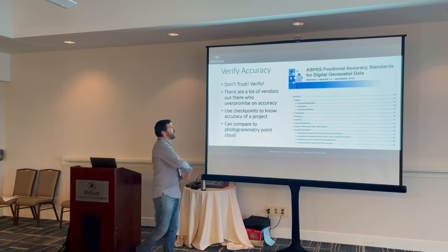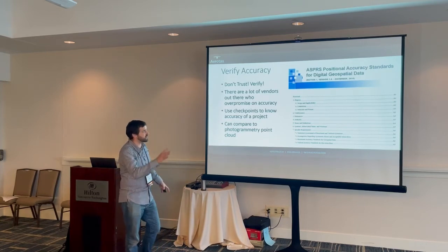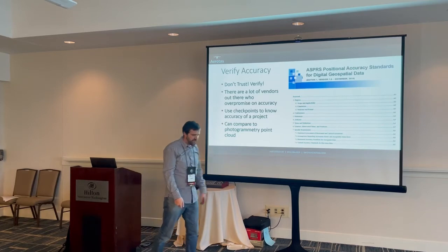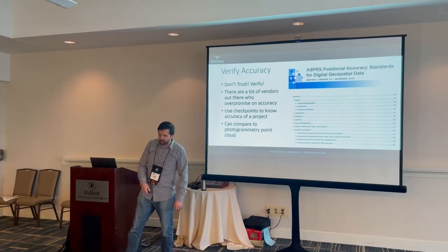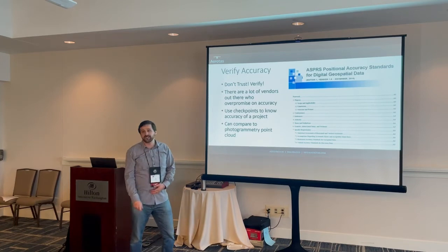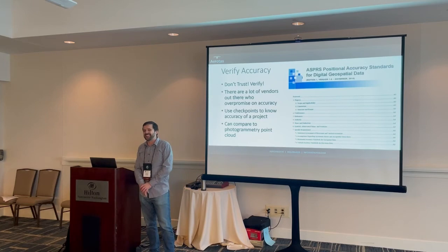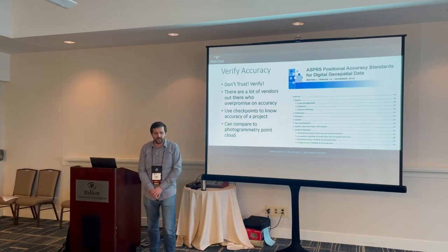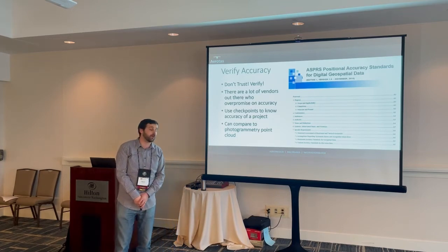Our accuracy gold standard is the ASPRS Positional Accuracy Standards for Digital Geospatial Data, last updated in 2014. If you are a digital masochist like myself, that is 20-something pages of extremely academic analysis and standards for actually measuring and validating accuracy data. It was published to be sensor and methodology agnostic, so it actually has a lot of LiDAR systems in there.